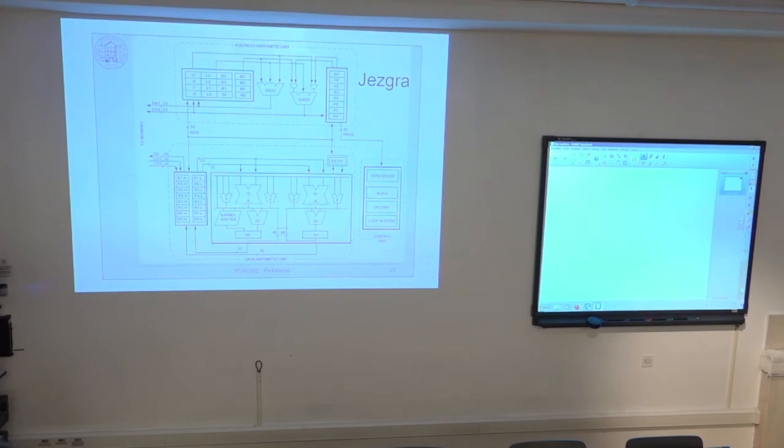So this data address 0 can be generated either based on this set of address registers or with this DSP-based set of address registers. Okay? For DA1, it can be only this one. Okay? Only DSP. DAG1, DA1, only DSP registers. Okay, now that I have two effective addresses, what I do is fetch from memory from these two addresses. Of course, if I have only one bus to the memory, one address bus, one data bus, and I want to do two fetches, it must be done in 2 cycles.